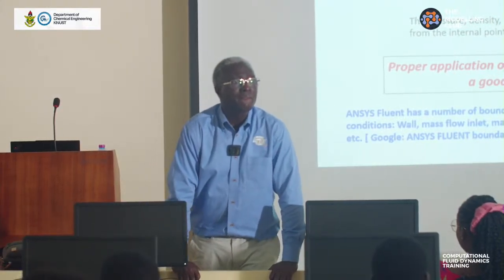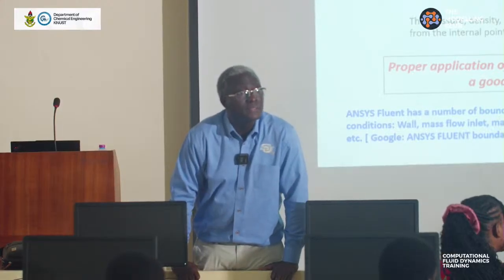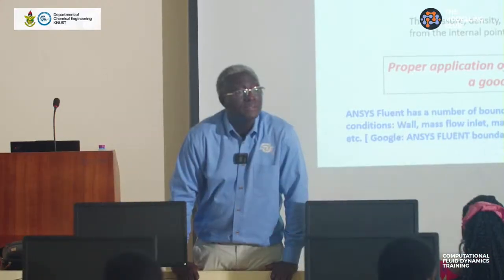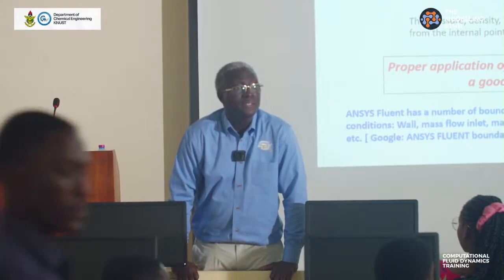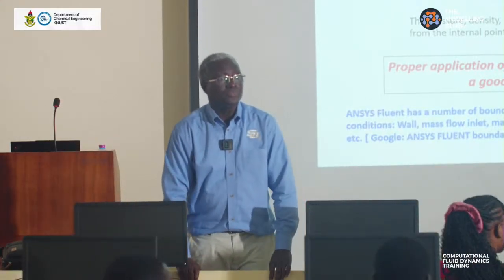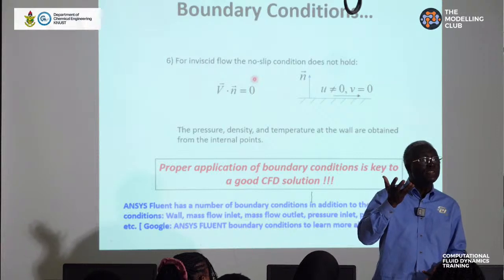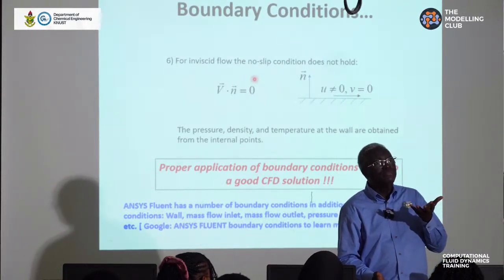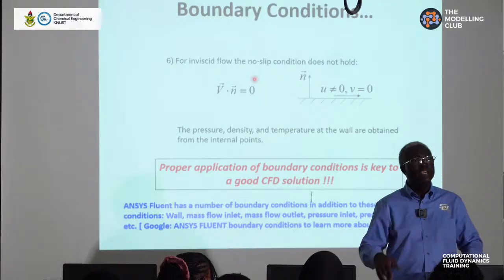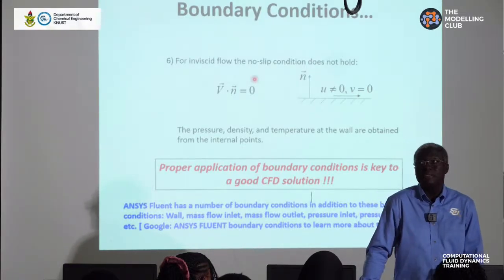Is it like adding and subtracting source terms from the equations for the different phases? Yes. So I'm thinking, assuming there's evaporation in the liquid phase, do I add a source term? You will have to add a source term. The source term will account for the rate of evaporation or the rate of condensation of one phase over the other. So there has to be a source term that couples the two phases together.